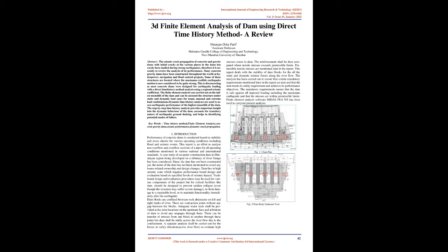Dam lies in a high seismic zone which requires performance-based design and evaluation based on specified levels of seismic hazard. Traditional design and evaluation procedures may be used for various components of the project, but critical facilities like dams should be designed to prevent sudden collapse, even though the structure may suffer severe damage, to limit damage to a repairable level, or to maintain functionality immediately after the earthquake.